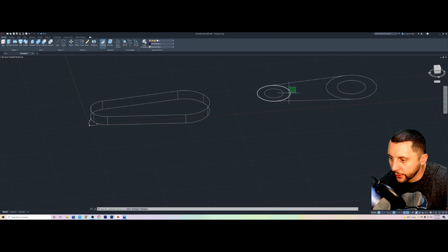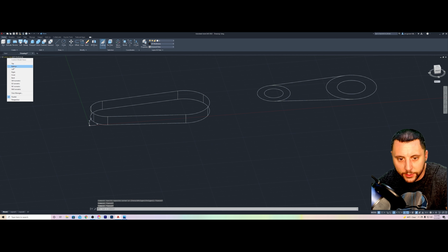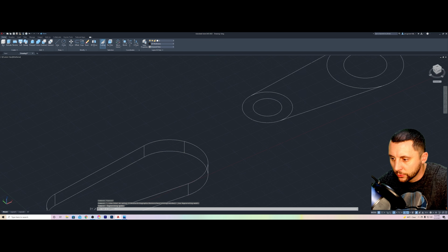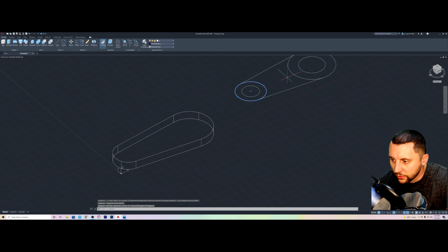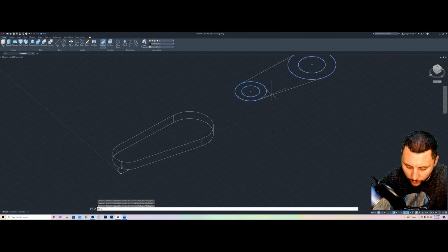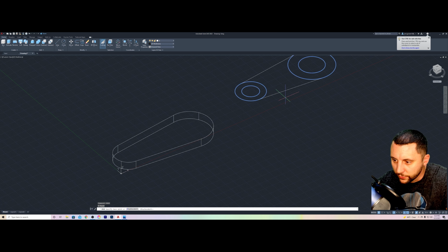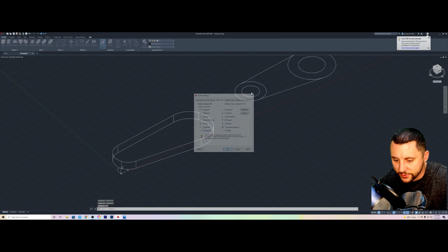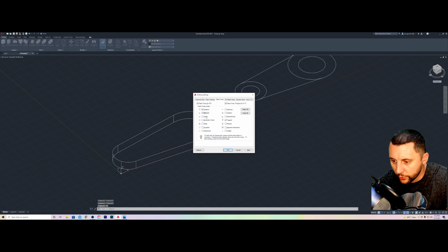All right, so let's get back to our top view for a second. And then just a little orbit. I'm gonna take that and that for now. Actually, we'll take the inside ones as well. And we're gonna move those over from the center of one of those circles. We gotta turn that back on, OS enter, turn back on endpoint, midpoint, center. We can turn tangent off now. I like intersection. And extension is good too.